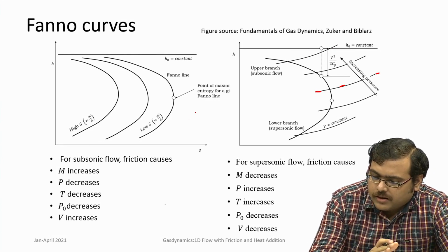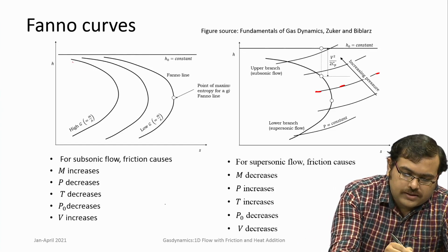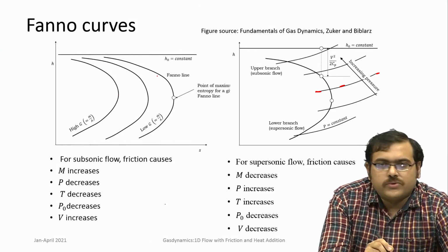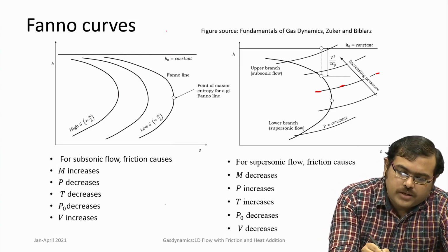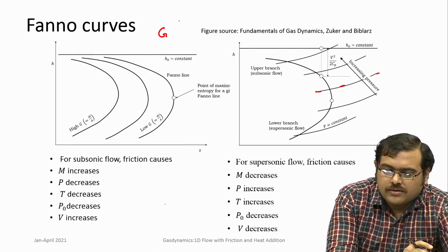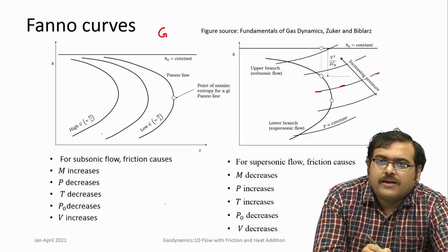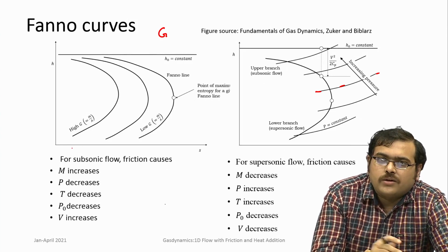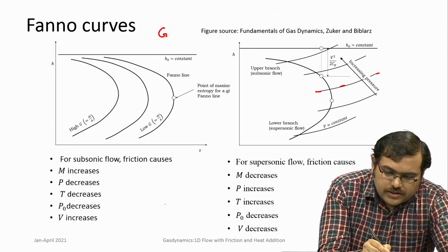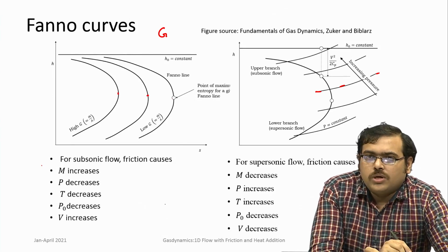These are basically pressure lines. So, as you go from left to right, pressure actually decreases. Also here on the right hand curve you have different plots where the only parameter that you saw in the Fanno curve was G, which is the mass flux basically. So, if you vary G, how does the Fanno line shift? Essentially it shifts in this manner, that as you go from left to right, G decreases, you get lower and lower G. Okay. So, at all these points you have this maximum entropy point, which corresponds to Mach number equal to 1.